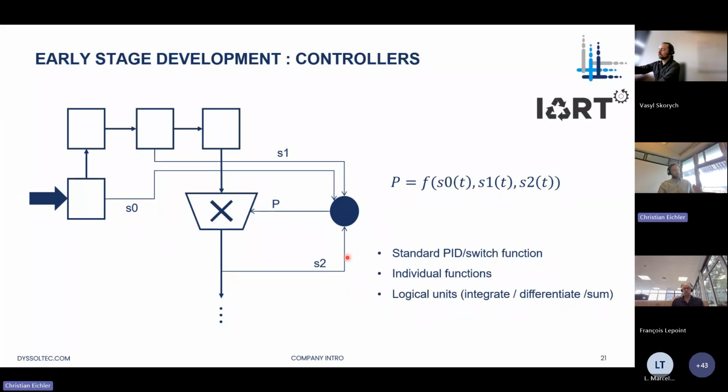which, of course, can have standard input like a PID controller or a simple on-off switch. But you can also build complex control strategies and functions, take them from different streams or different units, or even, as the next step, connect external servers to your controllers, get the input to control a unit, or use it as a signal for other logical units, which will also be implemented, like integration, differentiation, and summation.